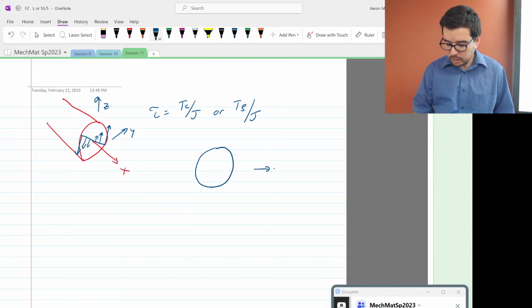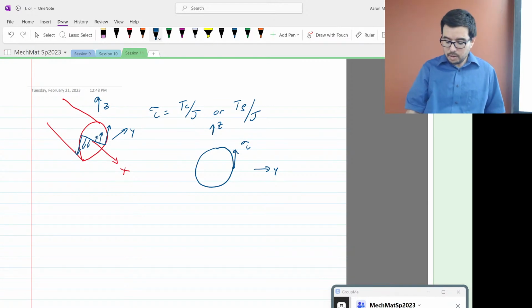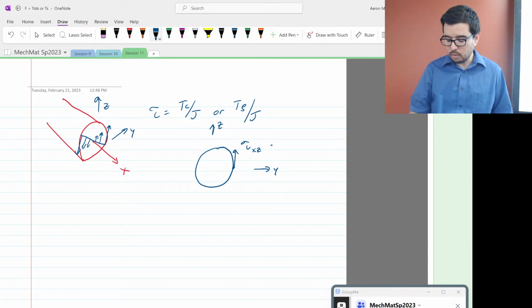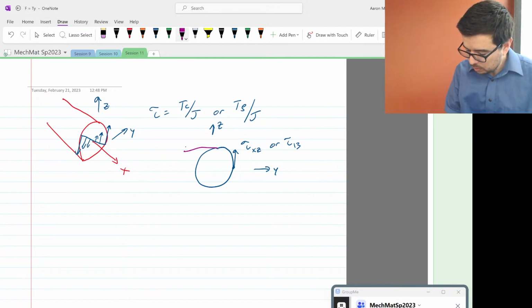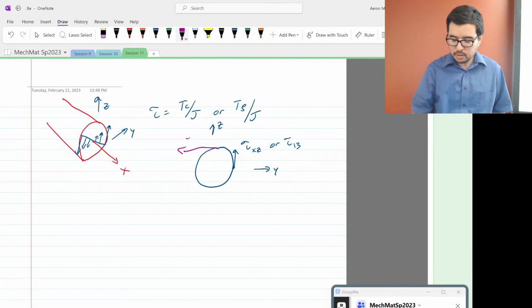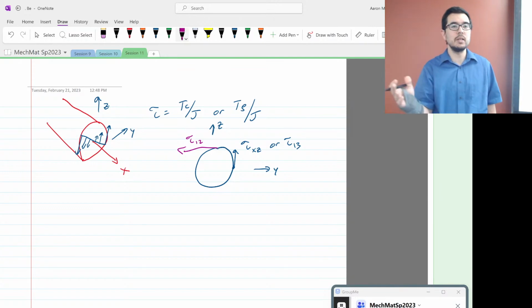and this is Y and this is Z, the maximum out here, which shear stress is that? The one I just drew. What would you give as subscripts here? This is tau. Yeah, tau 1, 3, tau x, z. So that one's going to be tau x, z, or tau 1, 3. Good, I think you're getting the hang of this. This one over here would be tau 1, 2, or tau 1 minus 2, but minus 2 is going to be the same as 1, 2.